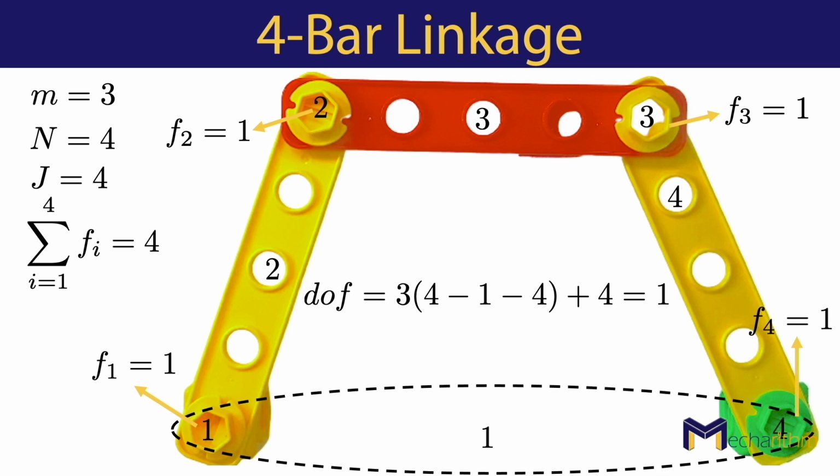We could also expect this result because suppose that the 4-bar linkage is a 3R open chain robot, that the 2 ends are pinned. So the 3R open chain robot, as we saw before, has 3 degrees of freedom. So 3 DOF of the serial chain minus 2 constraints gives us 1 degree of freedom. I reiterate that for the Grübler's formula to work, all the constraints must be independent. Now let's go ahead and see some spatial robots.